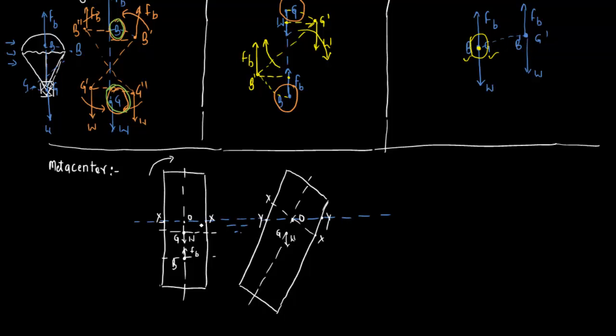So for the rectangle this was the center of gravity, that's why we define this as the center of buoyancy of the fluid. But in this case the center of buoyancy will be for the trapezium part. So let's suppose around here this B is going to shift. I know this is not looking good here, but for our calculation purpose this is okay. So B is going to shift here according to the trapezium. Okay, so for this trapezium body this is our new B, that I'm calling B dash, and the buoyant force will act here.